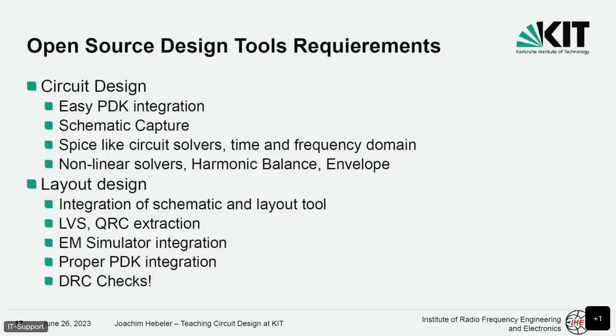We need, of course, all these solvers. We need all these nonlinear solvers, and they are somehow quite mature, but I've heard harmonic balance is still not really there. Envelope simulations, very complicated simulations. We have done EM simulations with 200-port S-parameter matrices, simulating very large circuit blocks. Of course, that's a very big problem for S-parameter simulation because then all these residuals can accumulate to large errors. Do these solvers handle these super large models? Can harmonic balance run on these super large models? Is this possible for our research, or is it more or less that you can build 2 transistors and simulate some transmission lines? Also for layout design, LVS, QRC extraction, very big features, very necessary.